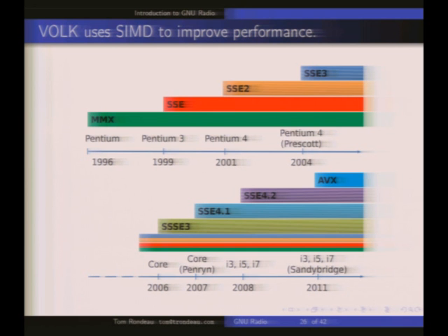As I said, it was originally intended for graphics used in multimedia, but it's easy to extrapolate from doing that graphical signal processing to whatever signal processing we want to do in wireless or radio. So there's this whole standard set of architectures here. This is just the Intel roadmap, kind of. There's other ones. There's ARM. ARM uses a thing called Neon. The PowerPCs, when they were more relevant, had Altivec, which the Cell processor was also very Altivec-like, a SIMD-ish programming language.